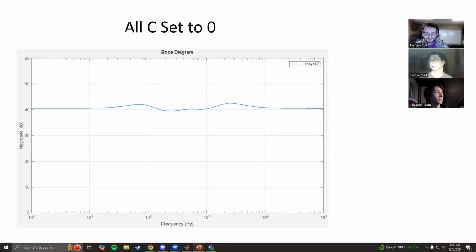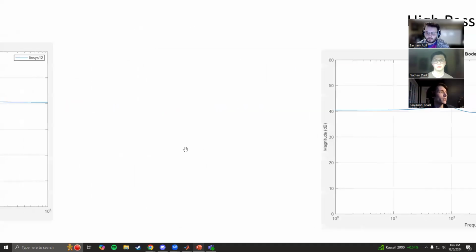We've got those bumps that are around our cutoff frequencies, and that's because of the overlap, because of the filters not being completely ideal with a sharp cutoff, since they have a slight slope to them where the bandpass and the other ones overlap. You get a bit of a boosting of the signals there. And then we can move on to the next one.